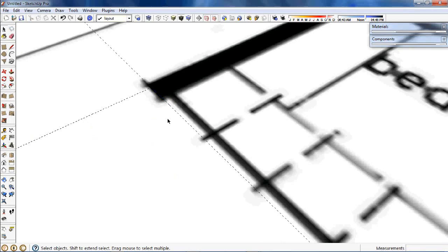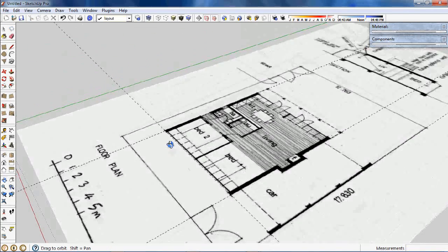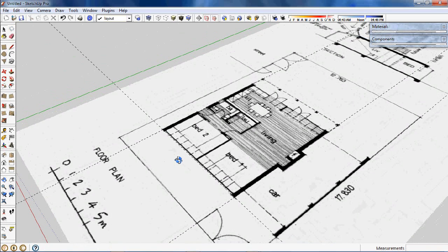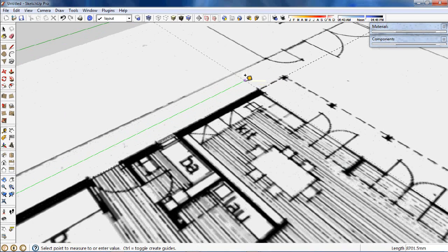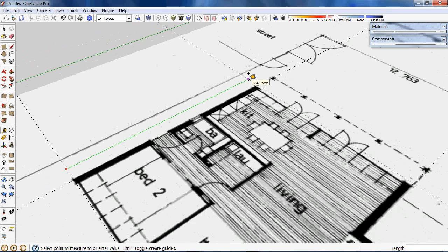Now, I'm going to do the same thing that I did before. I'll pick up my tape measure, I'll pull along that line here, and I'll drag out to the other end of that brick wall there. Now, respecting brick module dimensions there, if I go to 8750, a distance of 8750, because that's very close to what I'm reading here at the moment, I know that that's an actual brick module dimension, and there will be no need to cut any bricks. So if I type 8750 and press enter, there's my other construction line there.